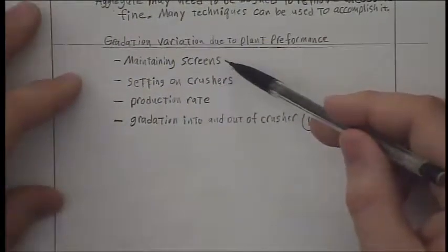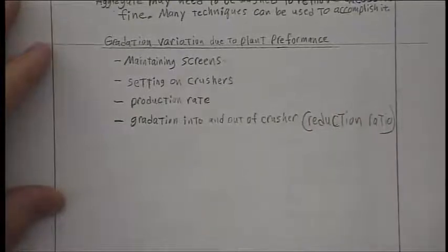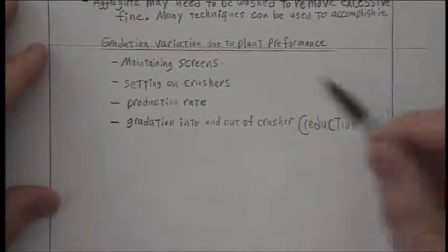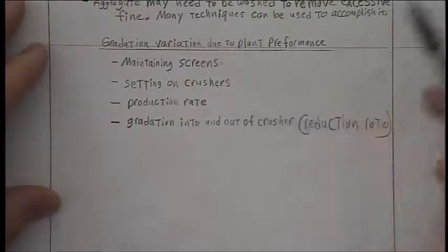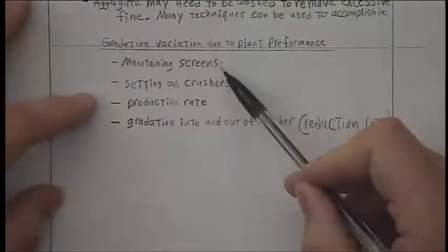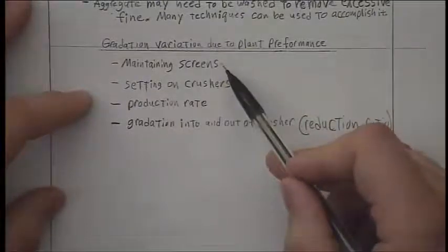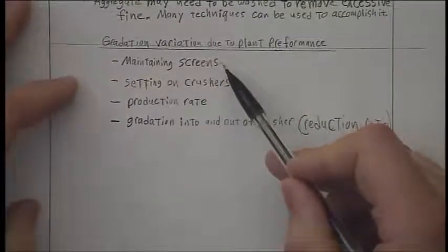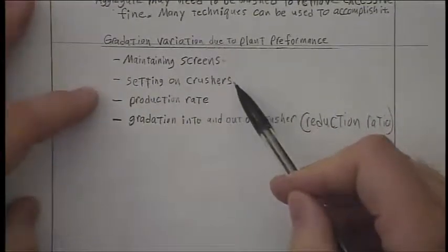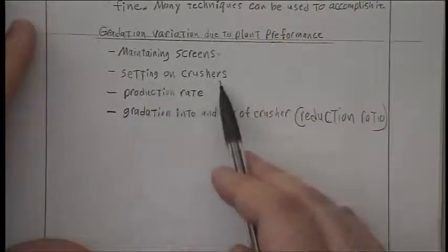I've found that quarries will just keep using screens for weeks or months that clearly have holes in them, so you aren't getting the gradation divided up correctly, but they make so much that you can't necessarily notice when they combine everything together, because it's a pretty exact process right now. Also the setting on your crusher matters.